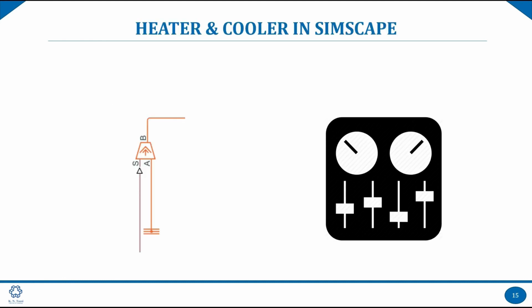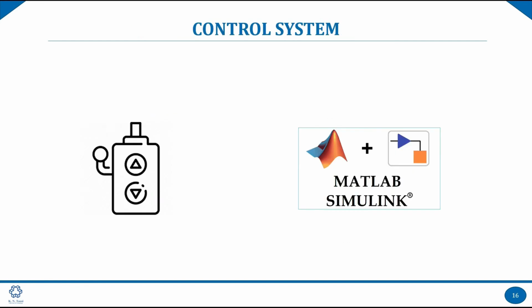In the projects that used SimScape for simulating the cooling heating system that I've seen, they use the controlled heat flow rate source block to generate the heat, and we must use a signal, and based on that signal it produces the energy and heat. It's precise and useful.